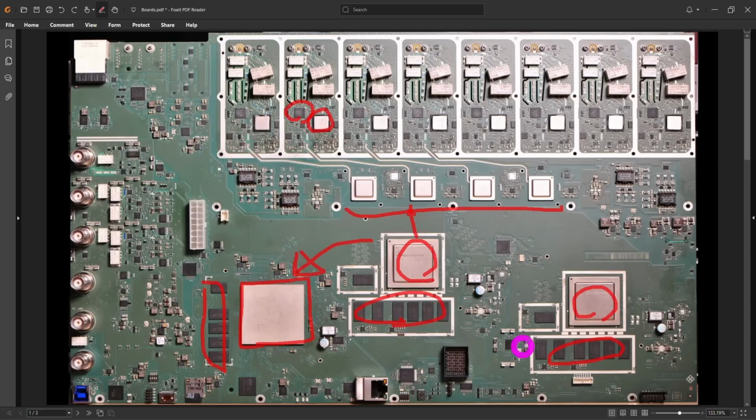And if you look closely, there is another item over here that's also inside of a cage. This is actually a dual PLL with 8 independent output clock generator. And that's not the one responsible for the data converters, but nonetheless it is a 100 femtosecond grade part, allowing you to provide synchronous clock to these 2 DSP front ends.